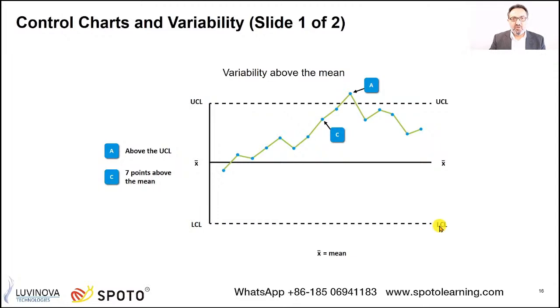For example, if I need to deliver this device, which is my device that I'm using to move between slides, and the agreement was to deliver this device at a specific weight, which is a range between two limits, this is what you have here as a range. This is what we call the upper control limit and lower control limit. Then once you start production, you are going to take readings. This is the first device, second, third, and so on.